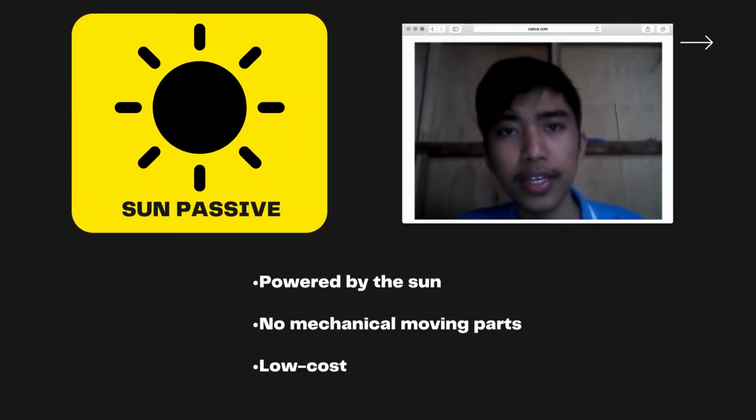In this study, the membrane distillation is powered by the sun. The sun creates the temperature difference and consequently the vapor pressure driving force. Also, the membrane distillation is passive, which means that it is self-operating and all processes occur without mechanical moving parts. This helps the device keep a low cost because of lower capital and operating cost.